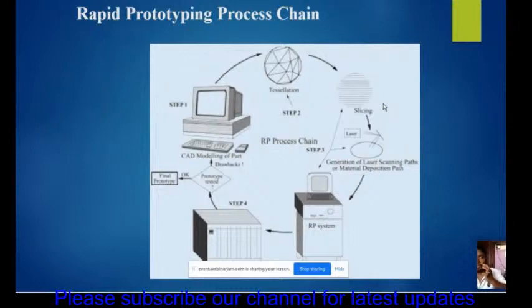In the slicing software only, you will be making some alterations for getting the perfect output of your model. See, there will be a preset. If you slice directly, that will have a preset configuration. But if you want to fine tune, or if you are looking for a more smooth finish, then you have to work on the slicing software, like print speed, or reducing the microns, or reducing the layer height, or increasing the microns in the way.